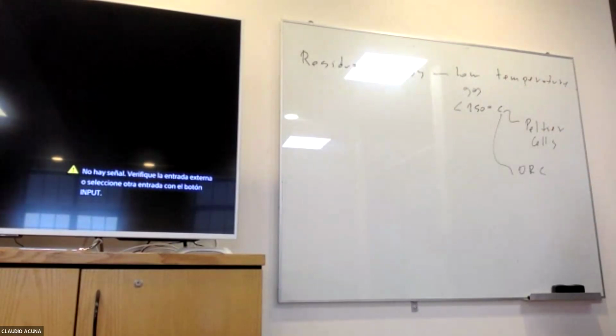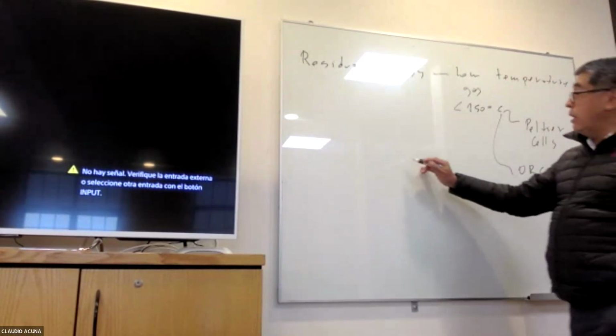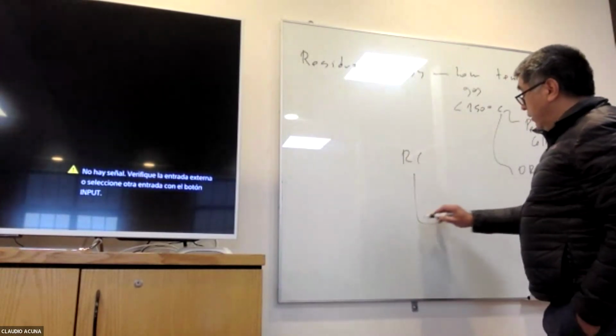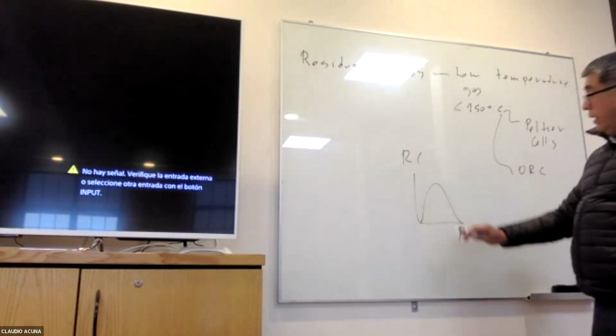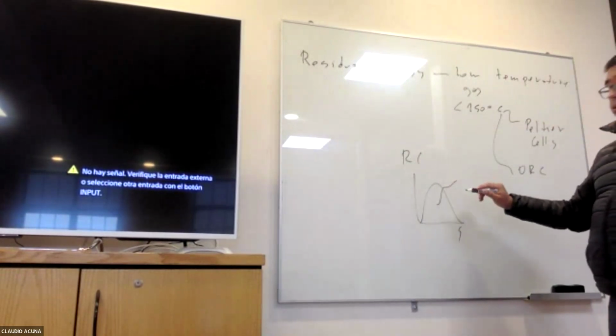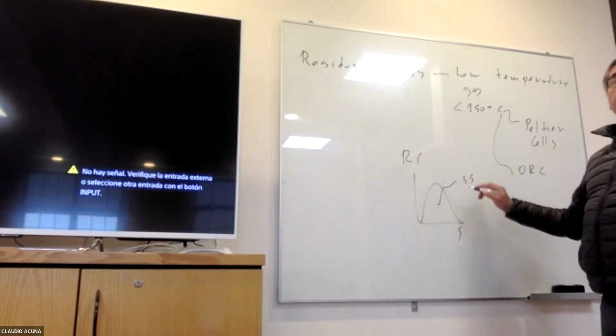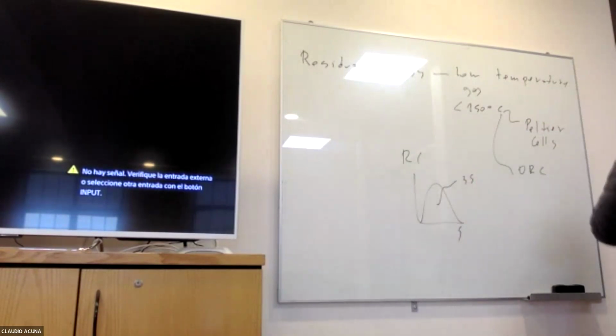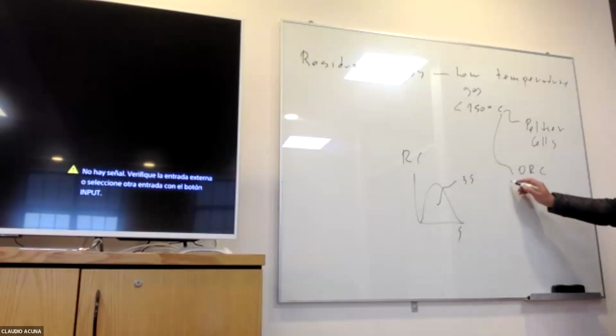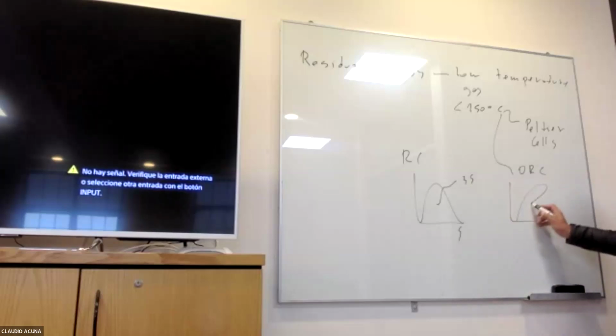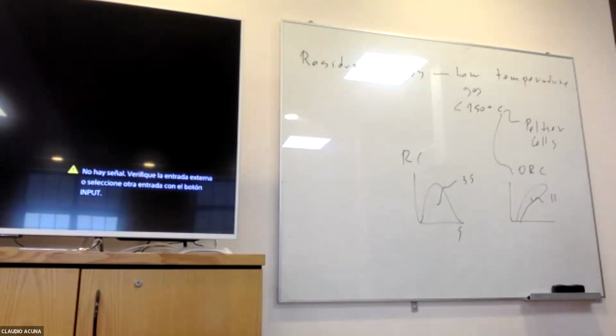We use isopentanol, we use butanol. If you compare with the traditional Rankine cycle, you have the typical bell-shaped entropy curve like this, so you can reach up to 35–40% efficiency from thermal energy to electricity. But if you move to an organic compound, it would be something more ugly, something like that, and then you get 11%, 12%. I'm talking about the organic cycle, also the Kalina cycle.